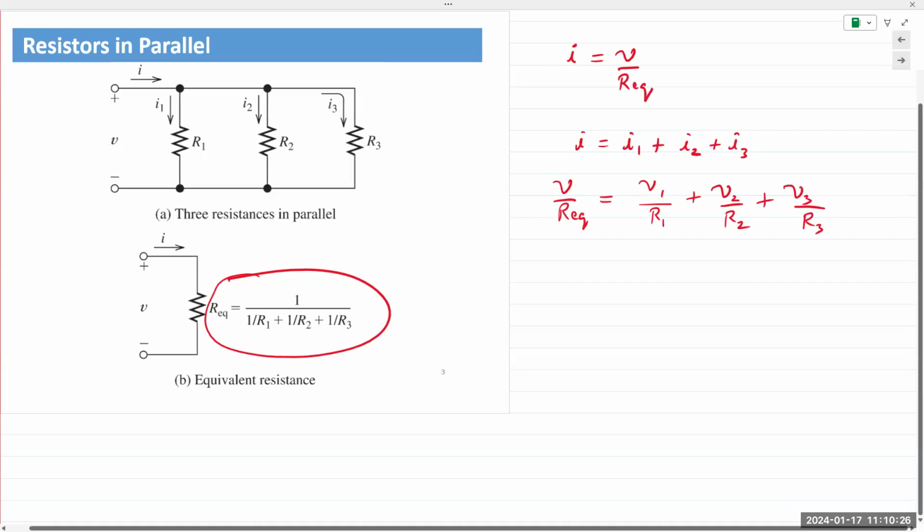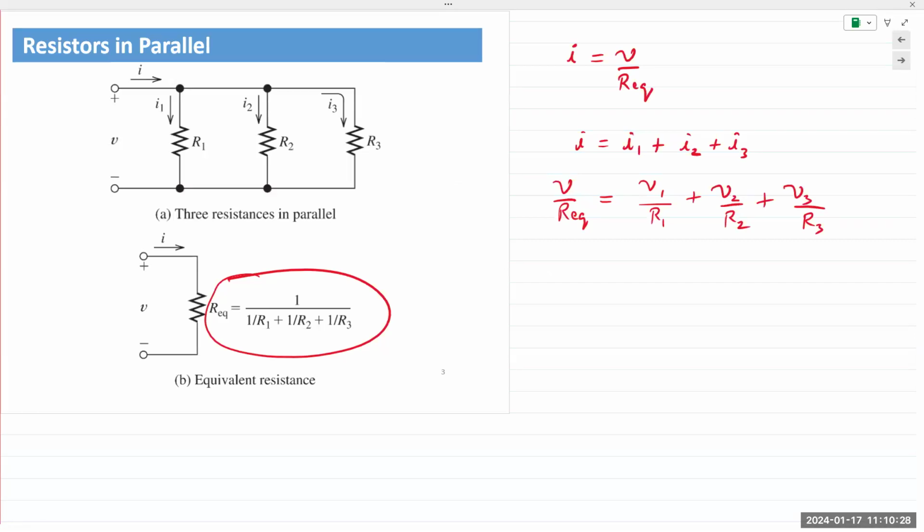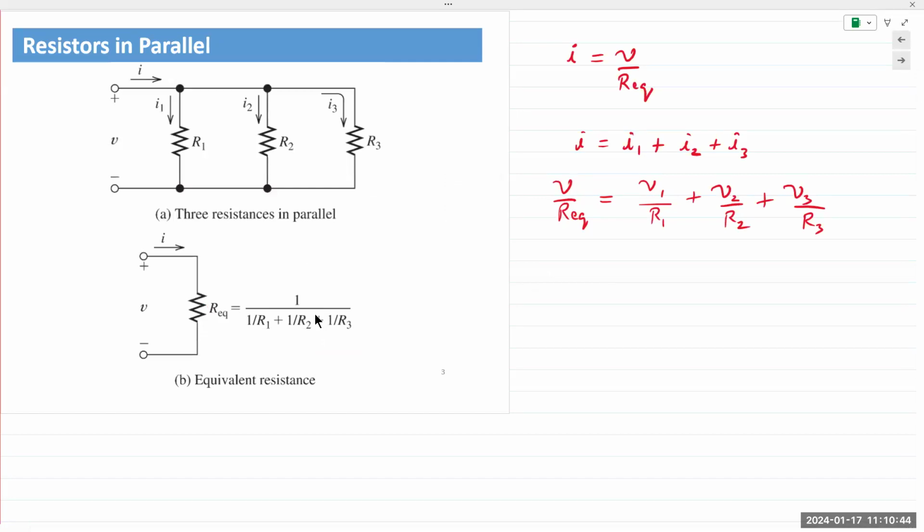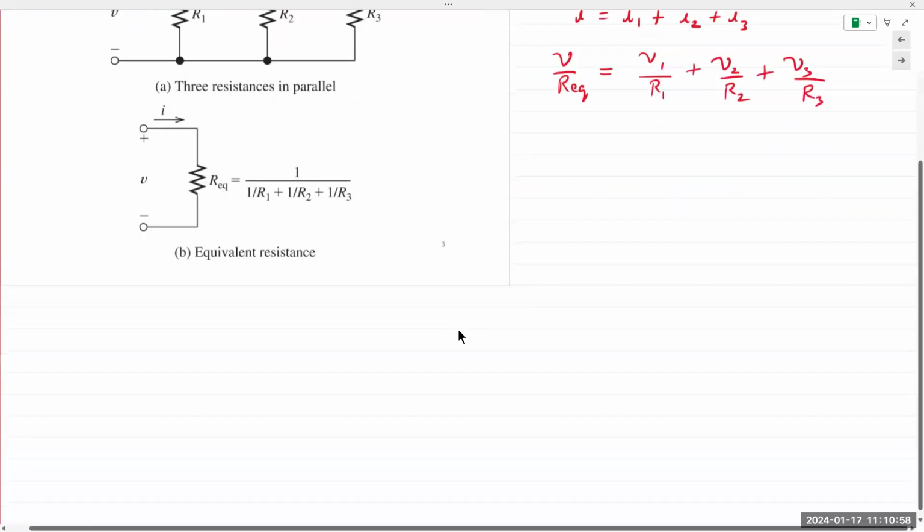Okay, REQ. Again, derivation is not important. What is important is that you understand this equation and more importantly, know how to apply it. Okay. So, resistors in series add up, resistors in parallel, you add up the reciprocals and take the reciprocal again. You can have this equation in your equation sheets. It's absolutely fine. There are 3 points that I want to note.